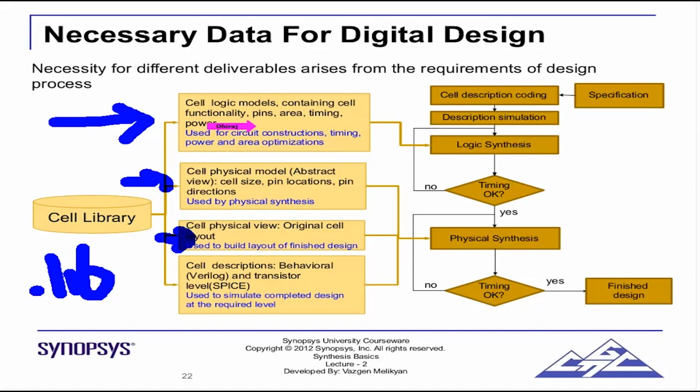Lastly, you need behavioral verilog models and transistor level models, spice models. This is used to simulate the design at different levels. So the behavioral model is used for function simulation, to verify that the design meets the function specification. Many people also do spice on some part of the netlist to make sure that the electrical parameters are good, the waveforms are looking fine.